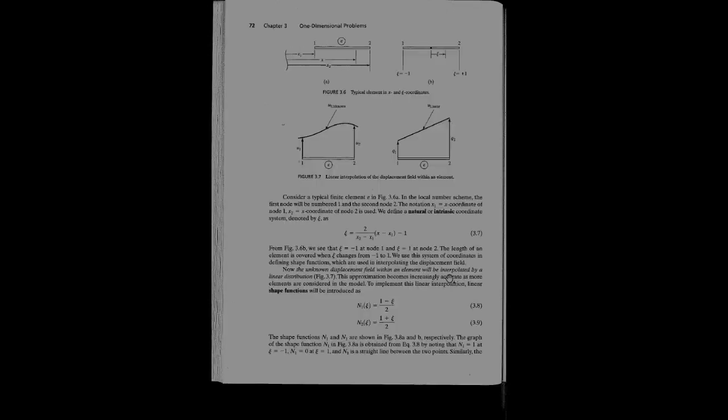Each of these elements, you can think of in isolation, and we know that on the displacement side they share nodes, which are things we'll still talk about as we go along. So this is just talking in general about element connectivities. Here they talk about shape functions. This is the example of the linear shape functions, and how they look over an element. Make sure that you're comfortable with this. This is how the displacement will be assumed to vary spatially using this shape function.